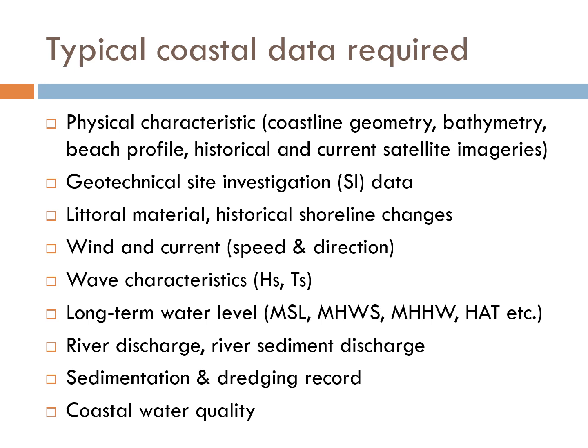We need the long-term water level changes represented by the tidal fluctuations that will include tidal datum such as mean sea level, mean high water spring, mean high water, highest astronomical tide, as well as the lower counterparts like MLWN, MLWS, MLW, and LAT. So please check again that you are familiarized with all these terms.